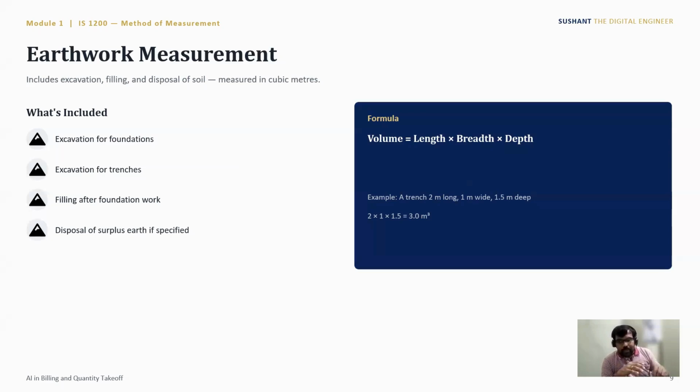But for excavation below lift one, there are some boulders, rocky kind of strata, so we need more laborious effort than what was required in lift one. So the rate applicable for that particular effort and equipment is different. So we need to calculate every excavation quantity lift wise. Got my point?